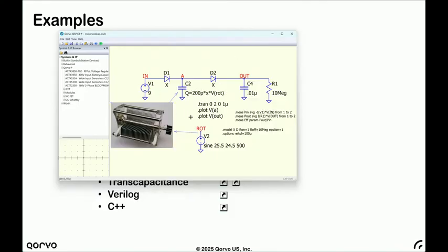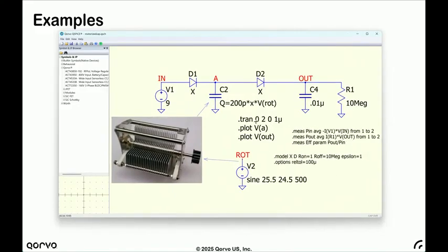And in this thing, this is sort of like a Van de Graaff generator, where you charge a staple and you run it into another voltage. You dump off the charge and you come back. This is an air vane capacitor. If you put, say, a 9-volt battery to charge it, and then put a motor on the spindle, then as you pull the vanes apart, the charge is conserved, but the capacitance goes down. So the voltage goes up, and then you can make a higher voltage. It's like a generator, except it runs on charge instead of magnets, and you need to prime it with some voltage source. Well, in LTspice, you could write that, but it wouldn't solve it correctly.